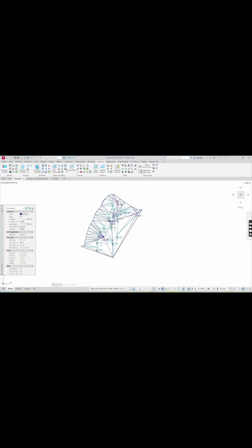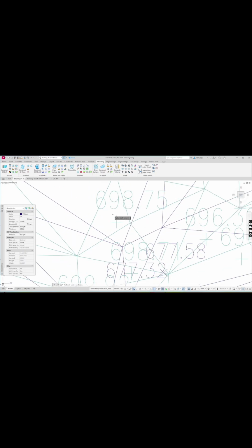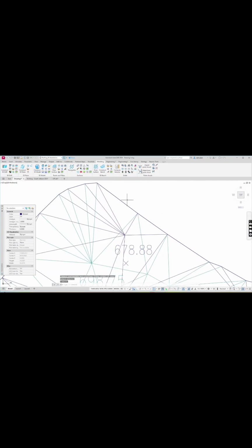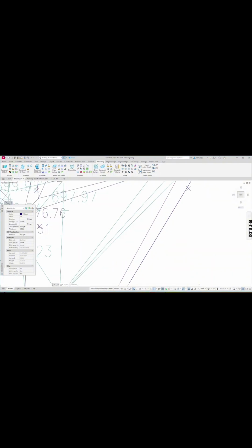For creating or building the wall, go to modeling, back to room and pillar, and then select create wall. It will ask for the back surface. I told you the cross symbol is for the back in green. I'll be selecting the back and the floor, click enter, and then it builds the wall.